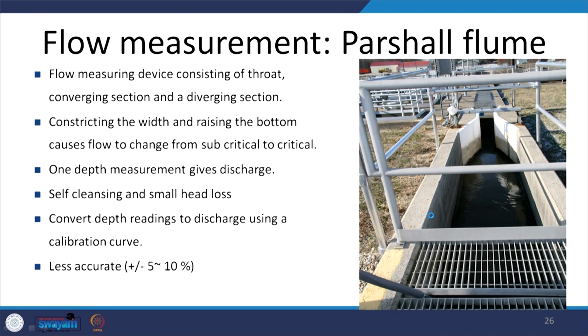So, flow measurement: Mr. Parshall's particular theory is working remarkably well. So, we construct what is called a Parshall flume, that is what you see out here. For this, obviously you need a considerable distance, depending upon the width of this flume, for creating the relevant flow conditions. Downstream also, depending on the width, you need to maintain some conditions so that the backflow does not affect the flow conditions through the flume. So, you need to have considerable lengths that you can provide.